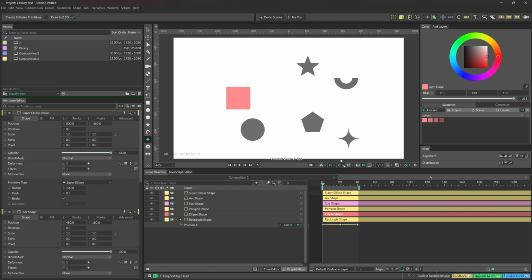Then we have snapping. You can enable layers to snap. For example, when I click V, go to the selection tool, right now, if it's not enabled, layers do not snap anywhere, right? I can't really snap any layer to anything. Let me have any of these layers selected. If I move them around, they don't snap to anything, right? But if I enable the snapping and I move the layers around, I can have them snap to another layer, which is very, very nice.